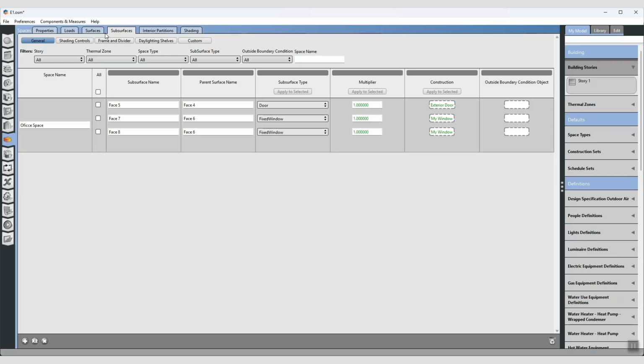In a simple building with only one space, creating a space type may seem unnecessary, since loads could be assigned directly at the space level. However, using space types establishes a structured workflow that becomes essential as soon as a model contains multiple spaces with similar functions. Now let's run the simulation and check whether everything we defined is being recognized correctly by OpenStudio.